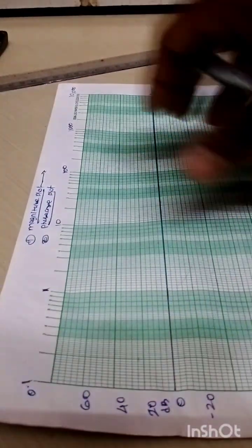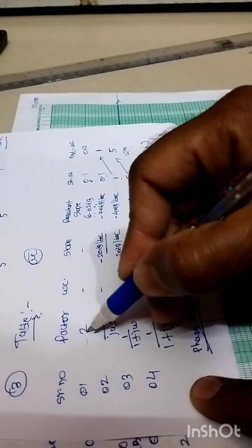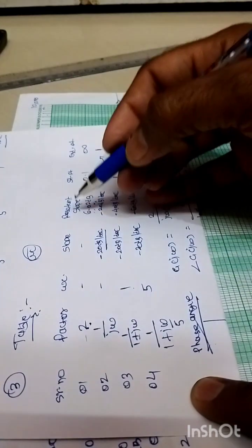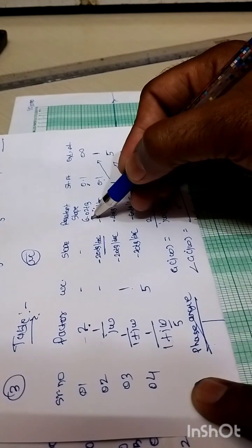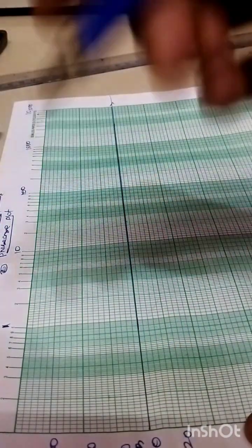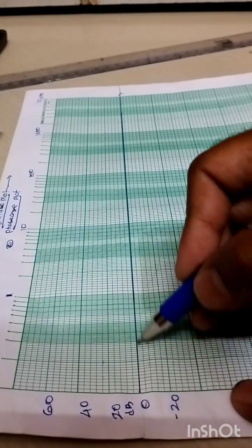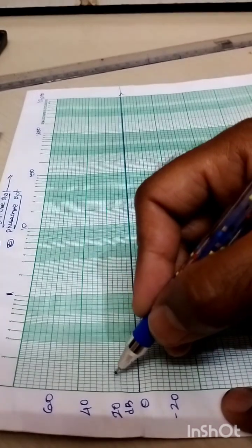So first, according to this table, we need to draw one line belonging to the factor whose value is exactly equal to 2, whose desired magnitude is exactly equal to how much here? 6.02 dB, right? As this is the reference axis, which is lying at 0 dB, right?